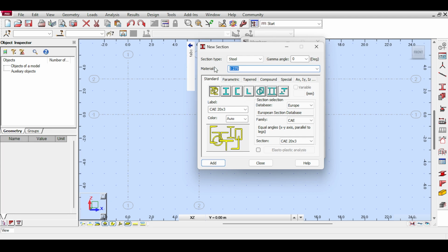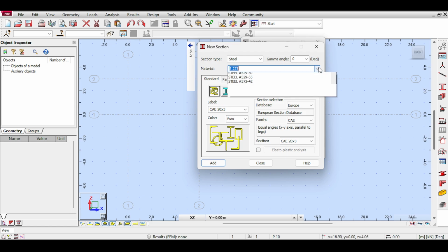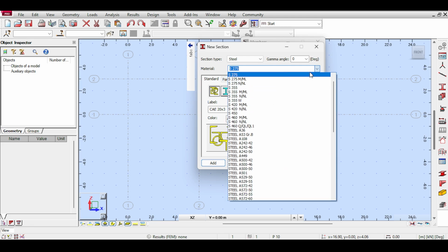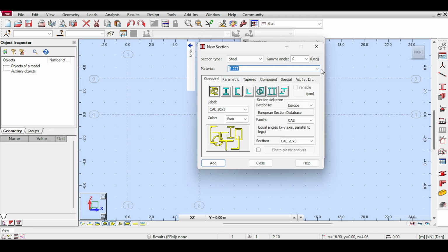Notice, this selection shall not be made haphazardly. You should also check with the local vendors if this is available or not. Because yes, you could assume any logical steel strength, but is it available in your region? Because if you assume something high that is not available in the region, then suddenly you run the extra cost of importing that stuff, which might be more than the cost of increasing the section that you're using. So please, before you select the material, check the availability from the local vendors. It's very important.